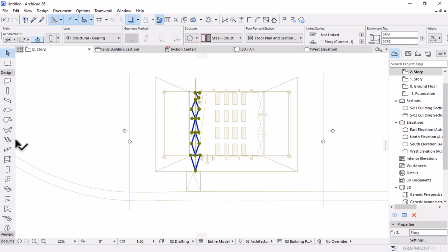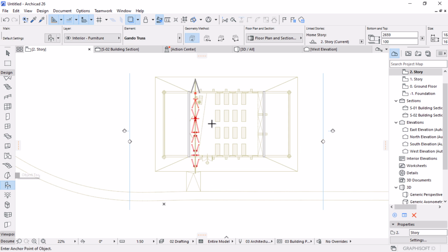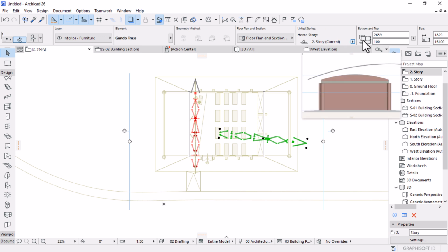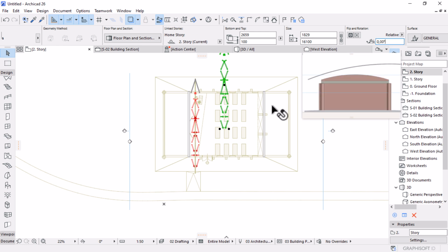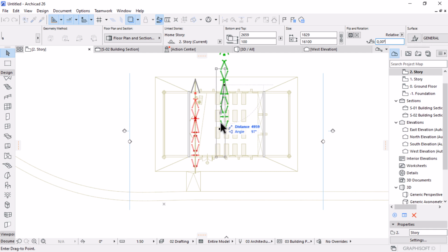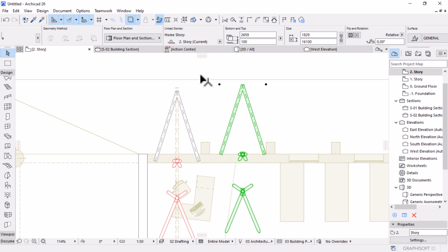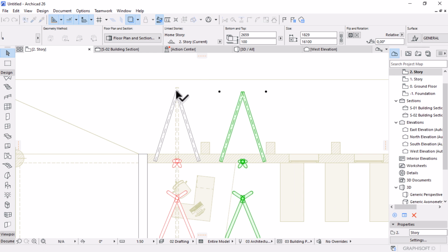Once you're done, you could load your truss, activate the object tool, and then place it there. Select it, make sure it's 90 aligned. Oh, sorry, let me make it 0, so that it can be positioned to this one here. They had to be aligned.